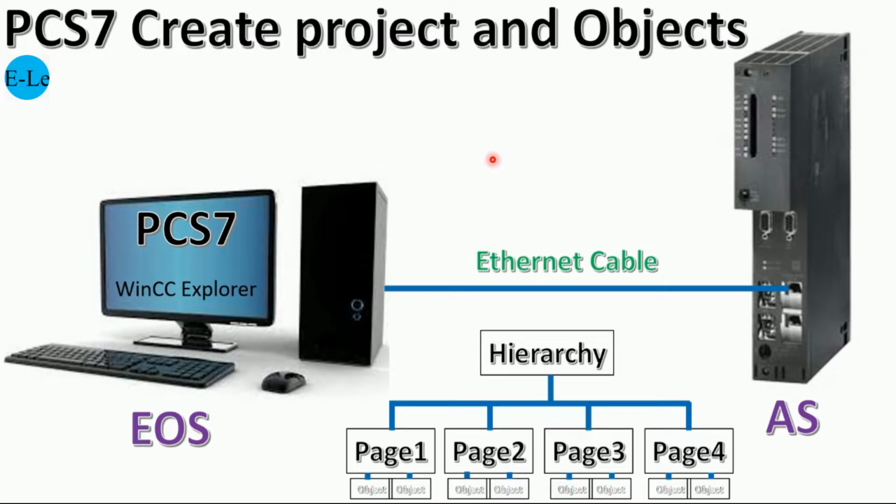Today we will create a new project for PCS7 to simulate with the objects, where I will create the hierarchy the same as plant 1, plant 2, plant 3 and plant 4, by using PCS7 and WinCC Explorer.